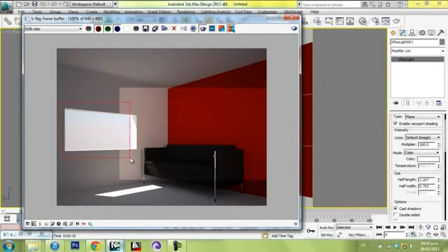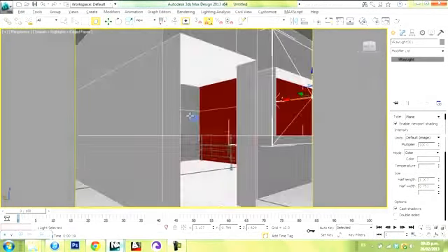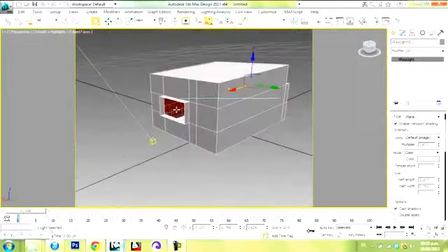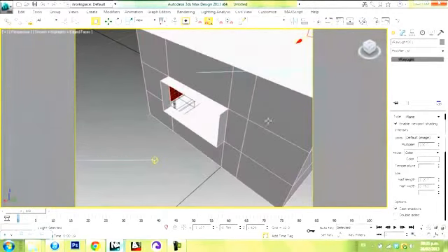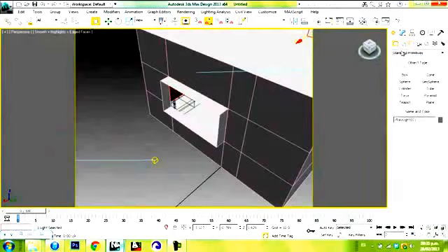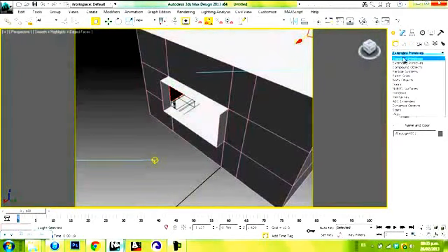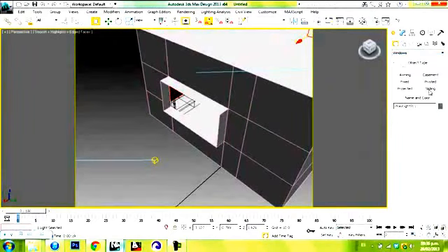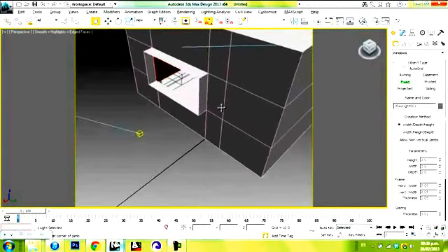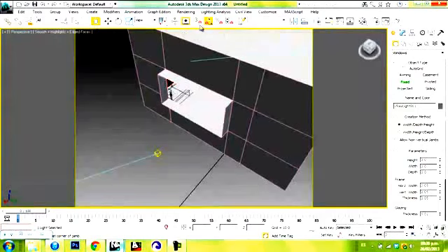So next we're going to add a window frame here, so I can teach you how not to obstruct the sunlight with our window. We have some kinds of window here. I use fixed window and select snap toggle.